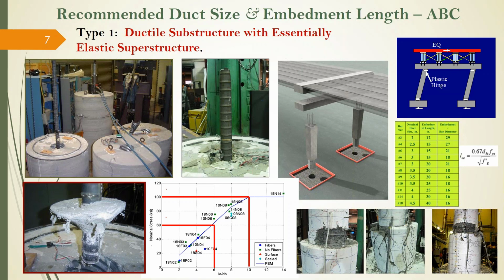That was followed by Highways for Life, which did the component test, the connection test, as well as precast column to shaft and precast column to spread footing connections. These are research projects that have been completed in Washington State and have been implemented, and are also partly covered in the ABC specification that will be coming up.